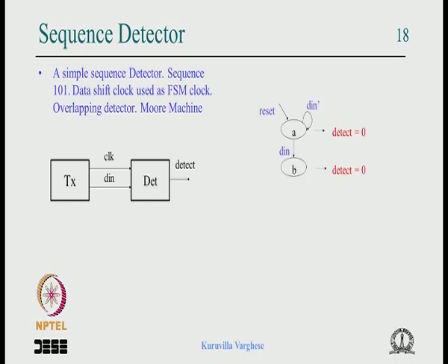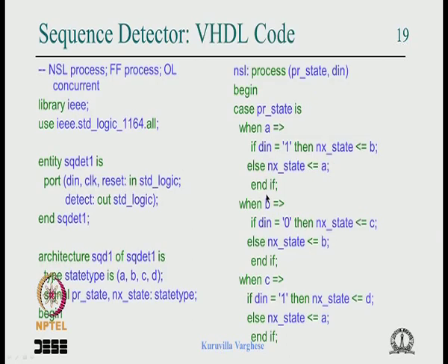What happens is that if we come and make some changes, suppose we find that this state diagram we have drawn has some problem and we have inserted 1 state in between, then it becomes 5 states, and whatever was 2 bits has become 3 bits, and you have to do a lot of changes. It's a big problem. So most tools allow you to define the present state and next state as an enumerated type, okay, so that you can easily change the state diagram.